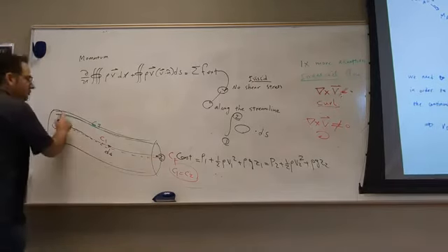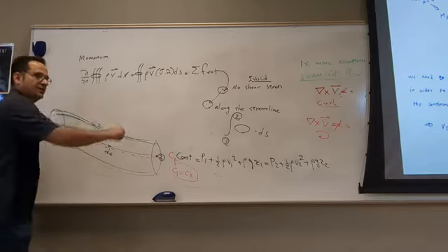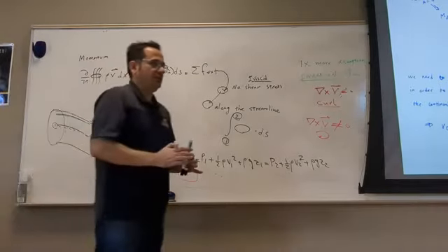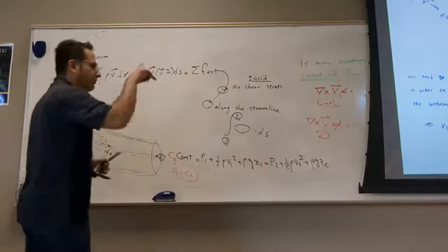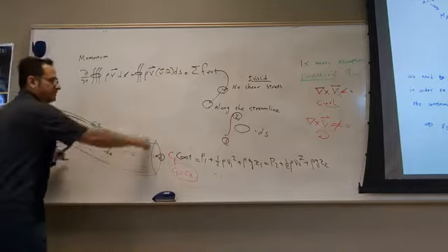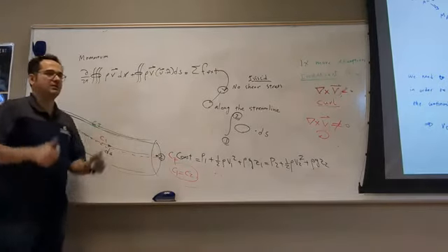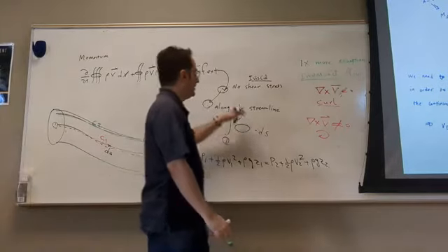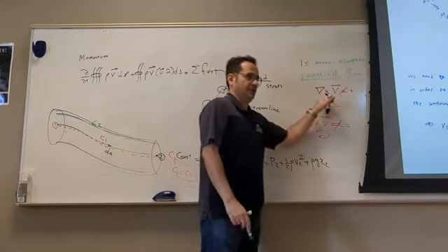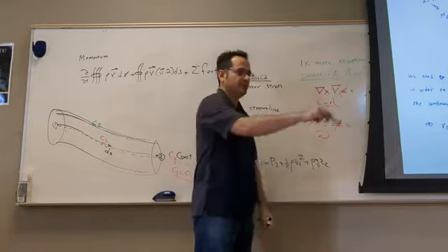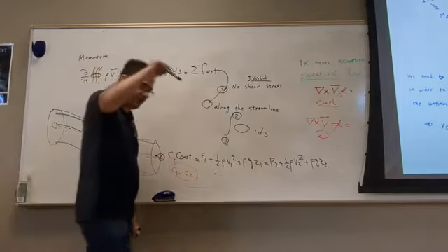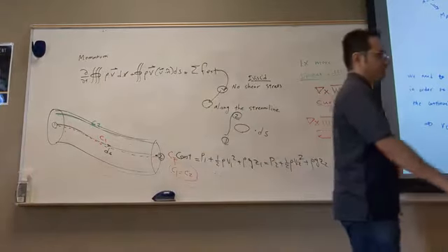That means you can write the Bernoulli equation about any points. You don't need to look for a straight line. So the summary is this: if the flow is irrotational, you don't need to look for a straight line. You can write Bernoulli between any points, and the result is still valid. But if your flow is only inviscid but rotational, you can't write the Bernoulli equation about any 2 points. You have to find a streamline and write the Bernoulli equation.